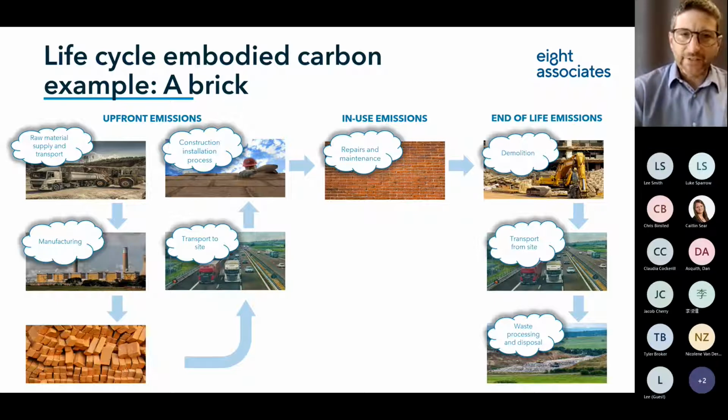And the emissions up to that point are known as factory gate emissions. So the bricks are ready to be taken somewhere where they're going to be used. And that stage clearly is called transport to site. There may be some intermediate spots in between, where they're with a supplier or something else, but effectively it's that journey to the site. And then you have the construction installation process.